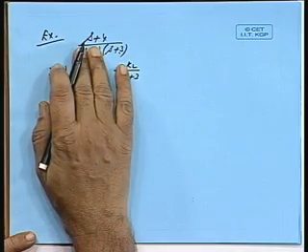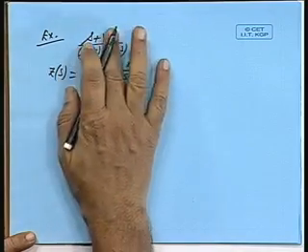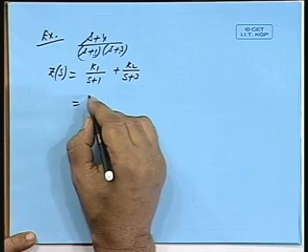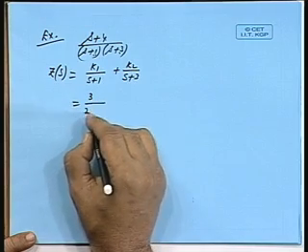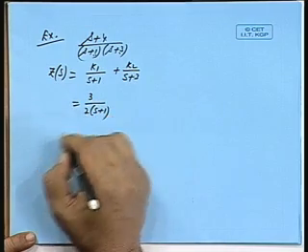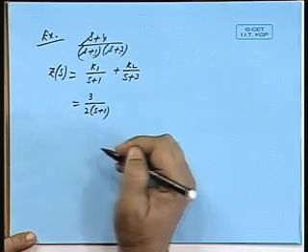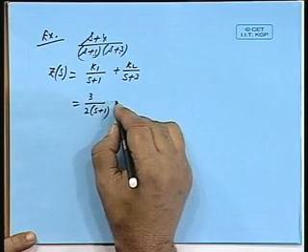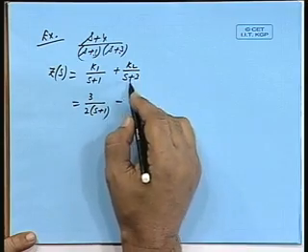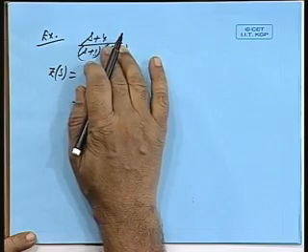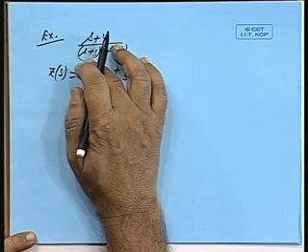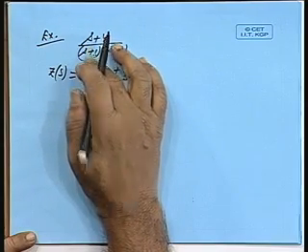Multiply by (s plus 1), put s plus 1 equal to 0. So, this will be 3 by 2, 3 by 2 into (s plus 1). So, this will give me an RC combination. Now, here it is K2, s plus 3 is 0. If I put, this will be 1, this will be 3 minus 3, so minus 1/3. So, it will not work.